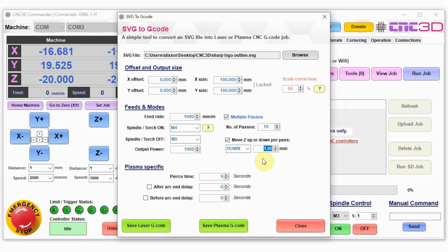We've mostly added this feature in here because sometimes when people try to use their lasers for cutting, they pretty much need to. As they go through and do a pass, it'll go part way through the material, and then you really want to drop that down a little bit just to make sure that you are actually able to get the same focal point through the actual depth of the cut. This might be a little bit of trial and error, but it's really handy that you've got the option to do it.